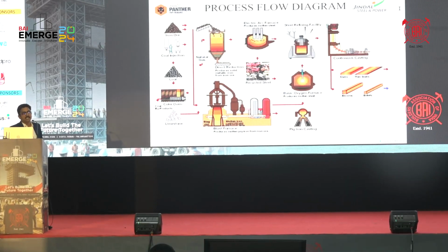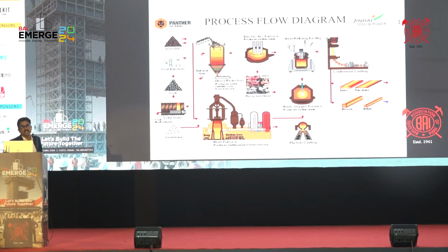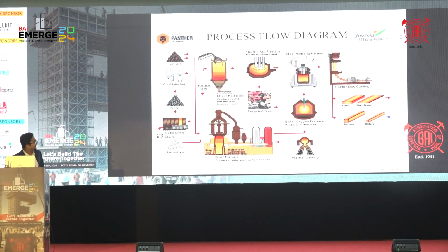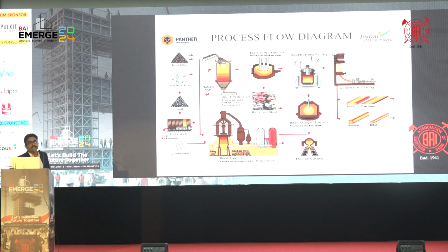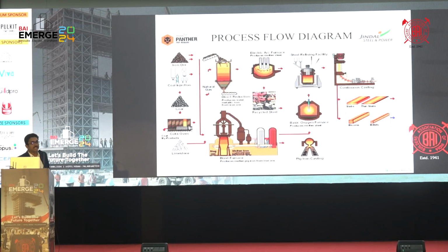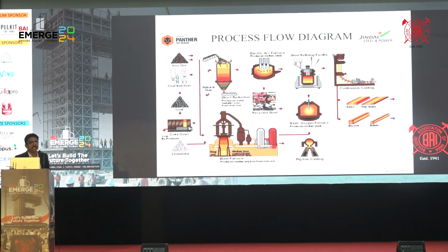This cannot be used directly in steel manufacture, so it is further refined in the basic oxygen furnace, where the required carbon is achieved, like 0.8 or 0.6% carbon from the basic oxygen furnace. But while we gain the carbon percentage, sulfur and phosphorus are unwanted materials. They are treated in the LRF, the ladle refining furnace, where we refine further and the sulfur and phosphorus are controlled.